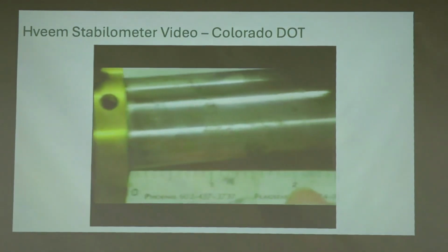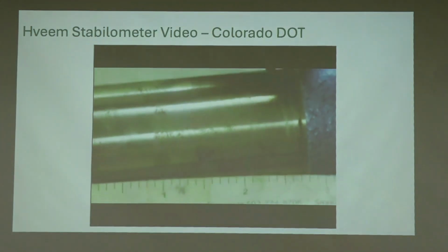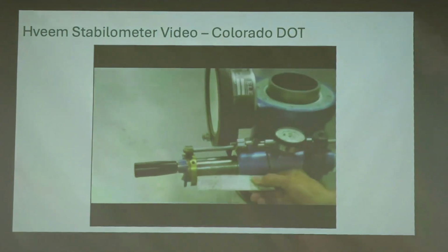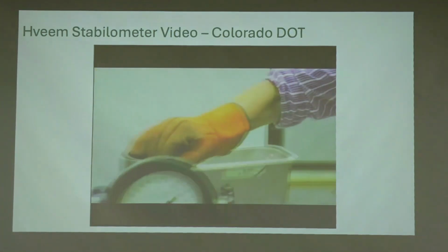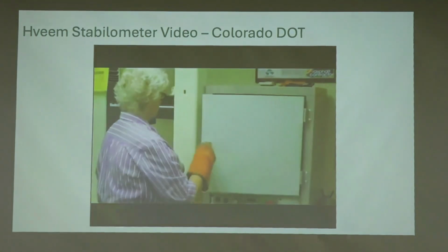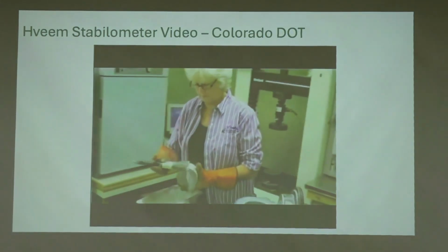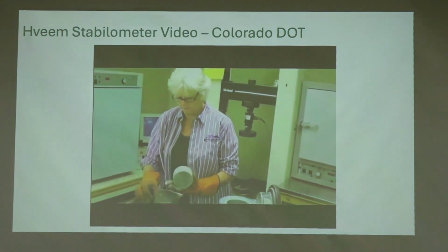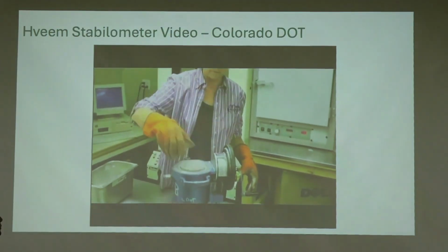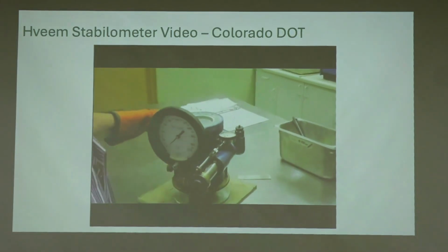So with the calibration cylinder still in place, with it set at 5 psi, you'll measure the exposed piston length, which needs to be 2.8 plus or minus 0.2, which tells you if there's enough oil in the bladder. So you'll be taking the calibration cylinder out then, and you'll be removing a specimen from the 140 oven, placing powder around the outside of your specimen, or you can actually put powder on the inside of the stabilometer bladder. Allow it to slide down into the stabilometer. If it doesn't slide down, turn the handle out till it easily slides down.